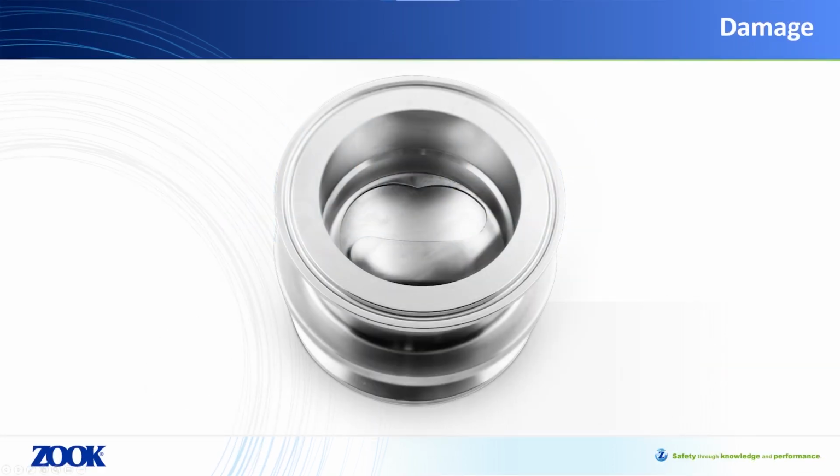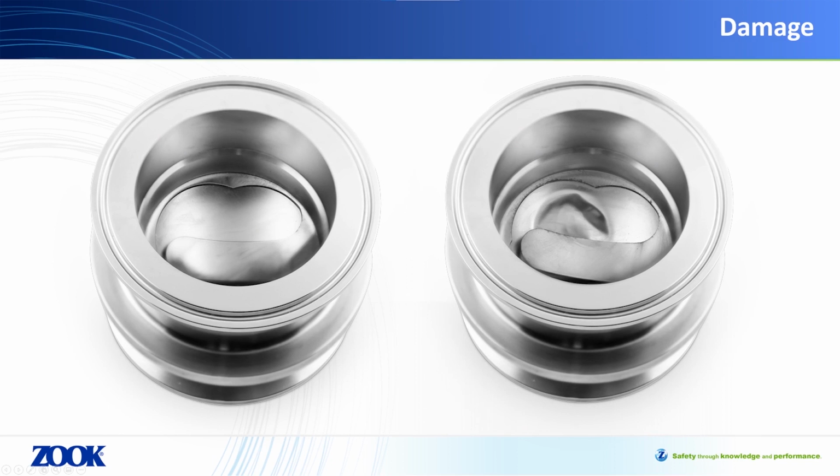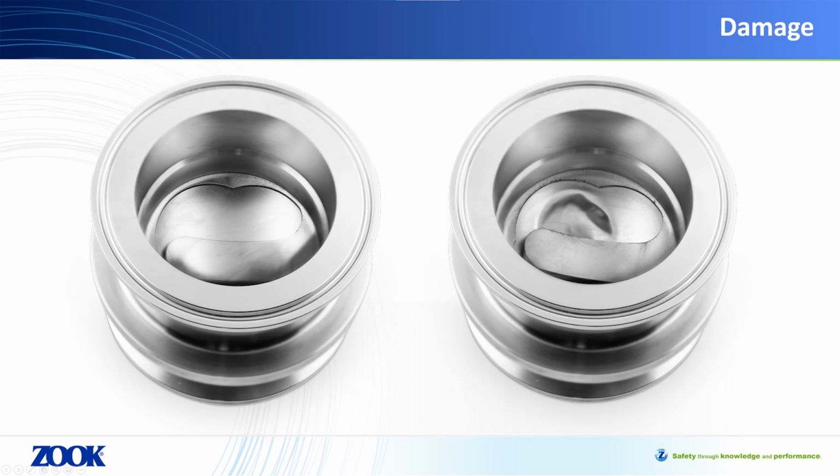Rupture discs are engineered products, but they can be delicate and fragile. Most rupture discs are what is known as reverse acting, and any minor damage to the disc dome, such as that seen in this picture, will negatively affect performance and cause the disc to burst or collapse low. Damage is a general term used to describe any negative effect on the disc itself.